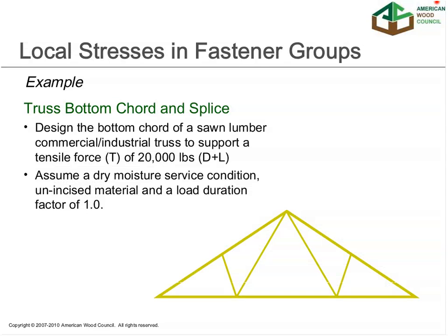We'll have a total load, dead plus live, of 20,000 pounds. And we'll assume a dry moisture service condition, unincised material, load duration factor of 1. So we're not going to have a lot of additional adjustment factors come into play for this particular example problem.